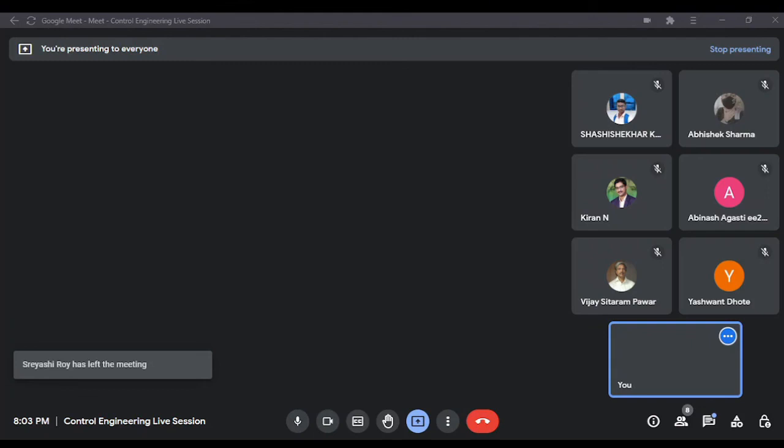Let's see the plots first. TC3. So this plot, when you see, you can see that this also settles clearly within 1 second, at least some 0.3 seconds around. But this has some overshoot. We'll have to check how much exactly. And we can see step of TC4. So that is now, this is even better. It settles faster and also has very little overshoot.